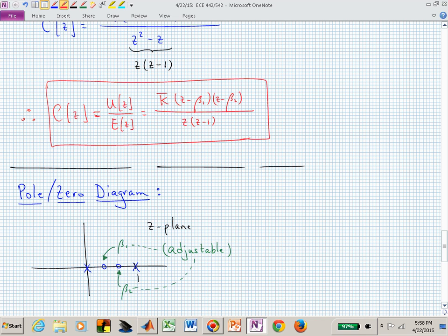What have we spent the last 2 weeks studying? Root locus. So those zeros allow us to shape the root locus. And what's the fundamental thing you're first wanting to do? You're wanting to bring all of those branches such that at some point, simultaneously, all of those branches will be inside the stability region or inside the unit circle. That's how you're hoping to select those two zeros.